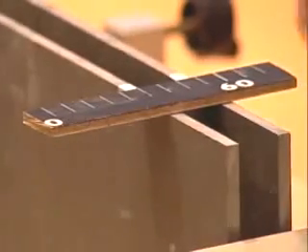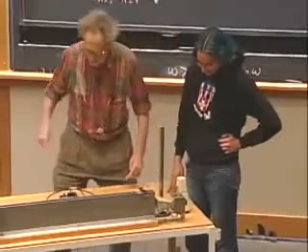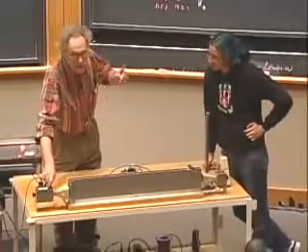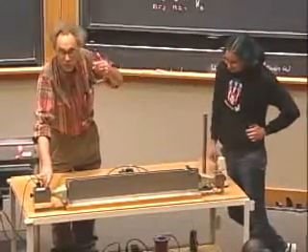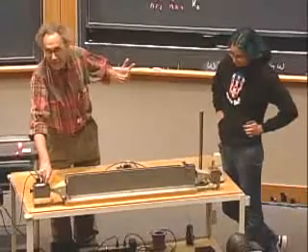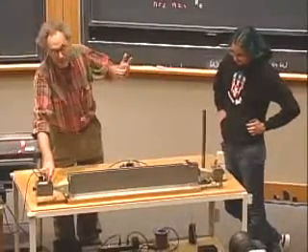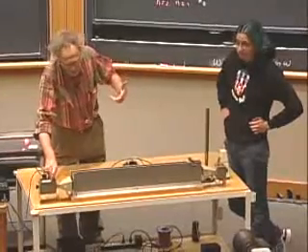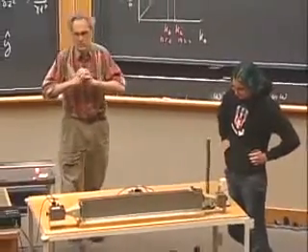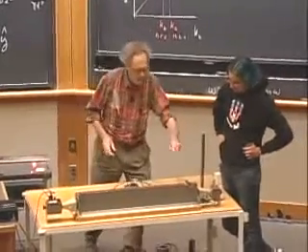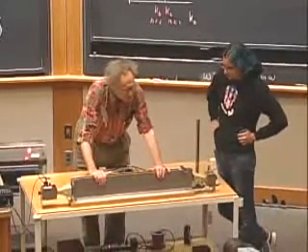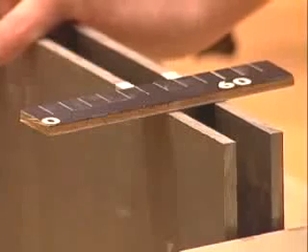This is a transmitter. It is polarized like this. Here is the receiver, which receives the polarized radiation like this. We modulate it with 550 hertz so that you can hear it. You cannot hear 10 to the 10 hertz. That's not the way that nature designed you, nor can I hear it. So this is 550 hertz. The gap is 2 centimeters. I'm going to make the gap smaller with my hand, and you watch it when it gets to 1.5 centimeters.